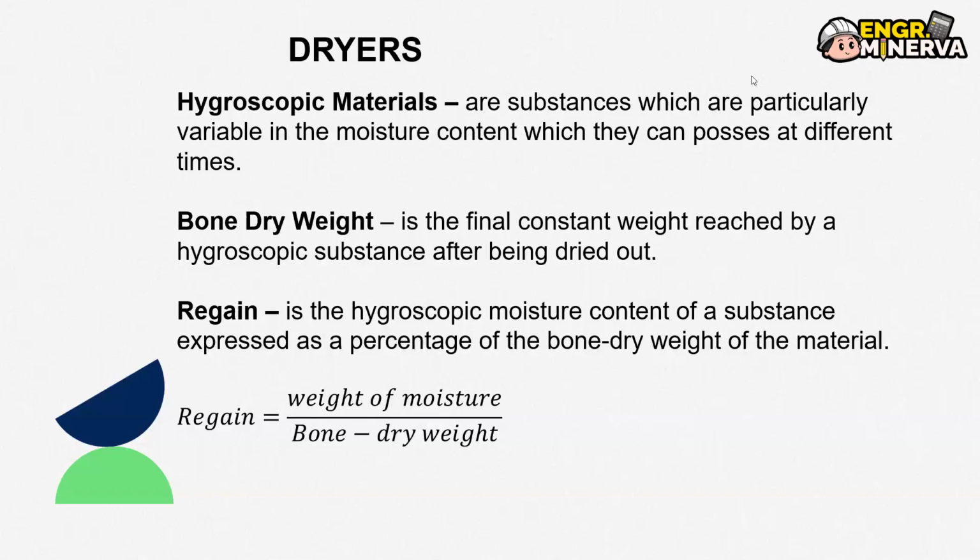Regain. So regain naman is the hygroscopic moisture content of a substance expressed as a percentage of the bone dry weight. So regain is just the ratio of the weight of the moisture divided by the solid weight of the object.